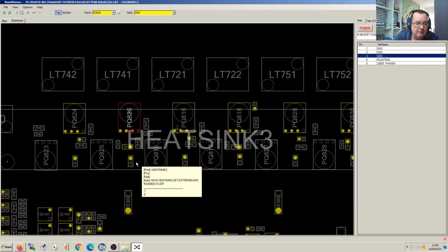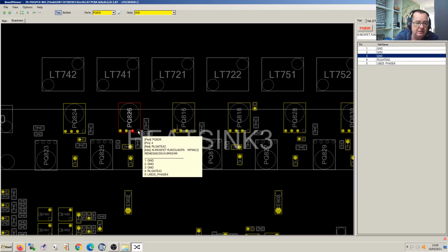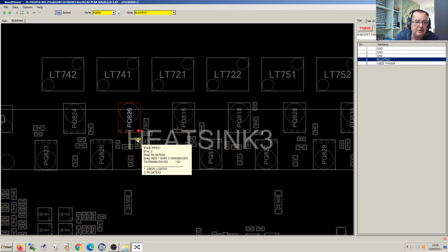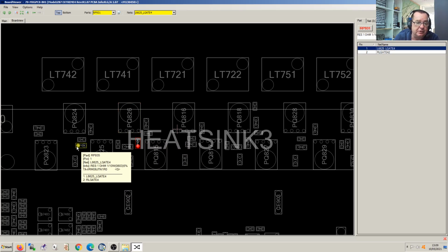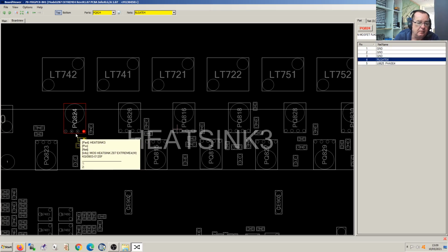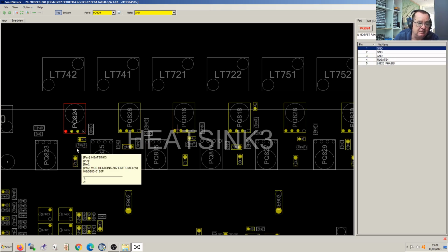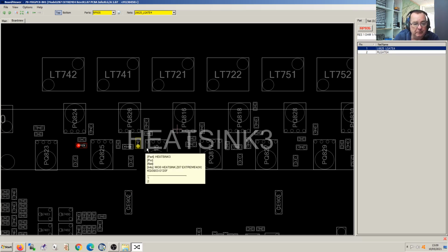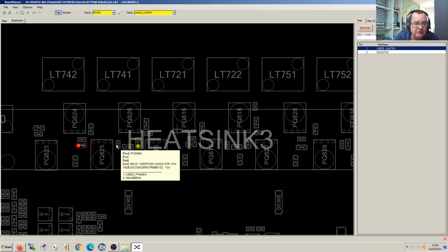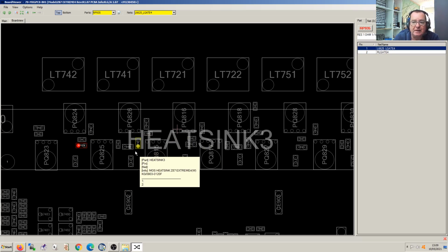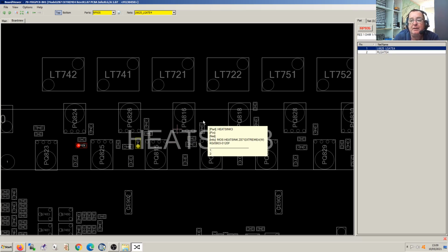Let's have a look where the gates go to. So let's go on one of the gates. Well, the gate goes to this resistor, showing you that. And it goes to the other end of the resistor, and it goes to the other resistor. So these two resistors are connecting together, and this one was probably going to the gate of the other one. No, it didn't actually. Yes, it did. Gate there. So that takes us so far, but okay, we know what's driving the gate on this.